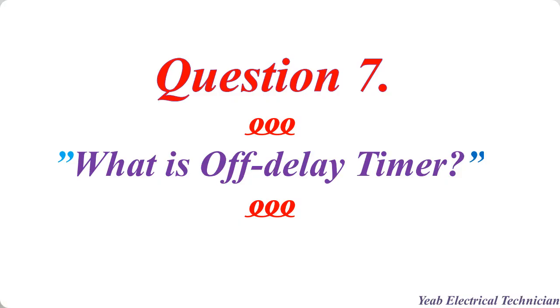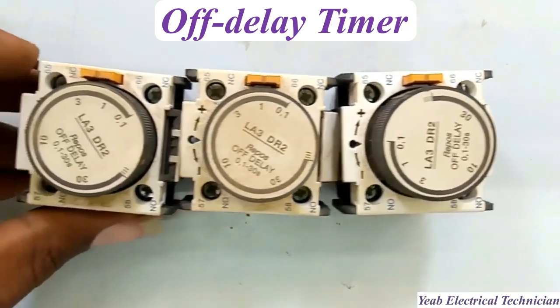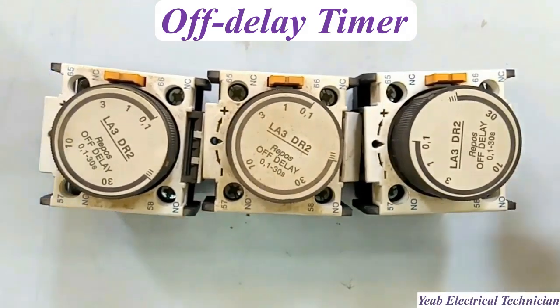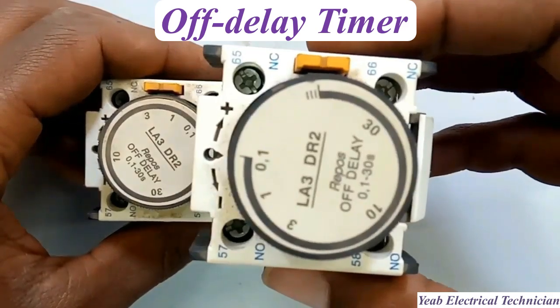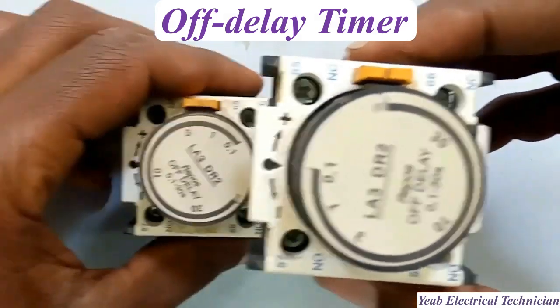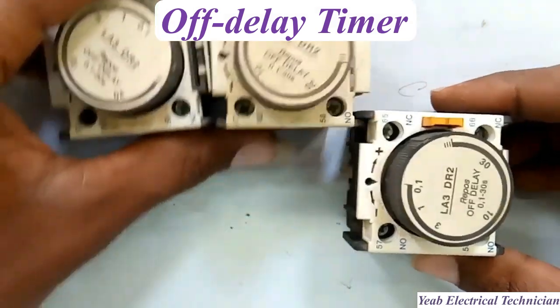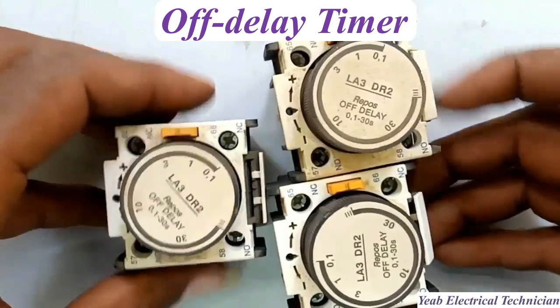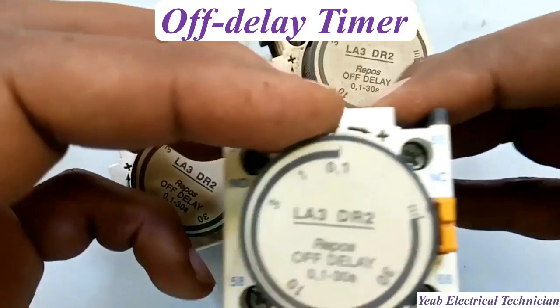The seventh question, what is an off delay timer? An off delay timer delays the deactivation of a circuit after the input signal is removed. When the input signal is turned off, the timer starts a countdown and the output remains active for a preset period before it switches off. This is used for delayed stop applications such as allowing a cooling fan to continue running after a motor has stopped.